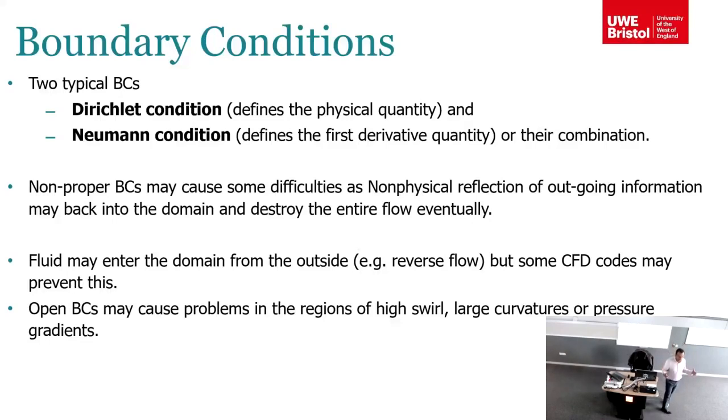CFD codes, some codes don't allow fluid coming from outside, so mass conservation is there. And sometimes don't have open boundary conditions. So I know in your problem you give a pressure boundary at the top. That's okay, but if you can avoid it, it's better.